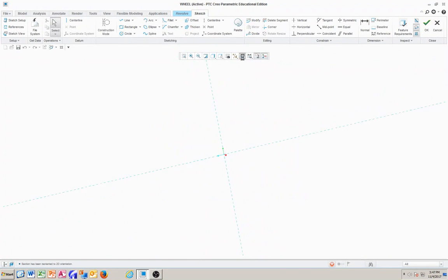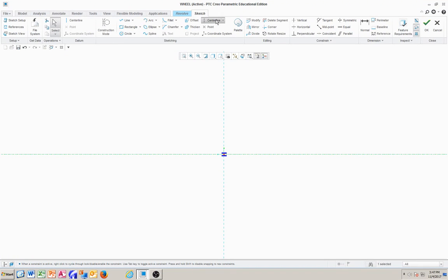All right, so we go to sketch view, get rid of all this display. Make sure that you put the axis of revolution, or the center line, we call it the geometric center line, on the x-axis, okay? Do not worry about the other center line here. You can place the center line on a vertical axis, but the wheel is going to be revolved around this axis here, which is the axis of revolution, okay? All right, let's get started.